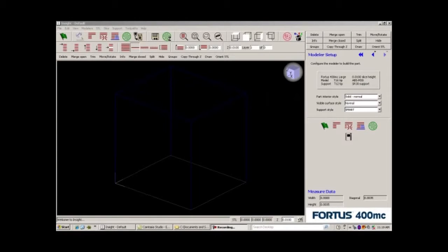Density, a lot of the work is done up front in your CAD package, as we briefly discussed in the presentation. So you want to make sure you design the part to have internal cavities and cores that fit in those cavities but are offset by about 1/1000th of an inch. Once you've got the CAD work done, we can now bring the file into Insight.